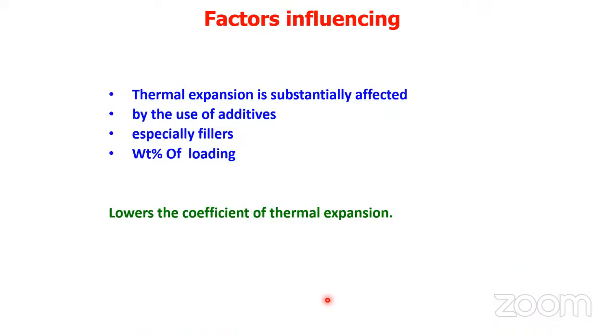So what kind of factors generally affect the thermal expansion of your polymeric materials? Thermal expansion is substantially affected by the use of additives, correct? Suppose you are adding additives to impart some properties or some strength to your polymeric material, that generally affects, or you can say restricts, the thermal expansion of your polymeric material, especially fillers.